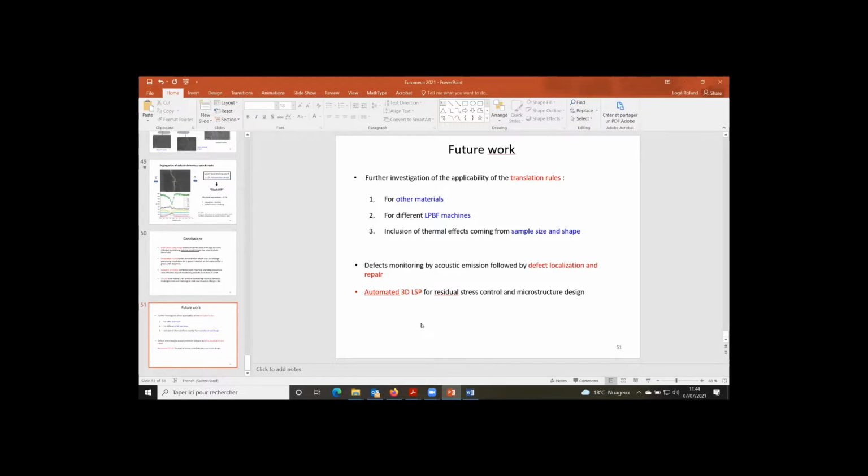That we have measured. It increases slightly, of course, the dislocation density. And because of that, when you do a heat treatment, it changes the behavior as well. For example, it may influence the recrystallization behavior afterwards. So there are many other aspects of this that we can use. Here I just illustrated the healing of cracks. Thank you.